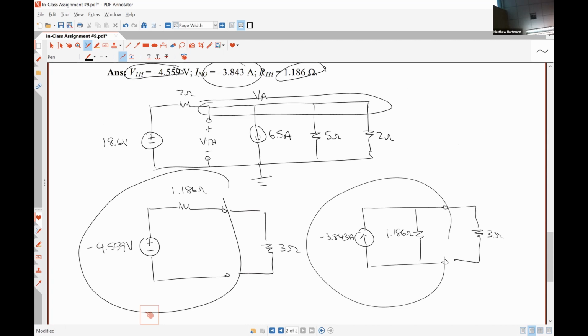So we made everything that isn't the 3 ohm resistor look like either this Thevenin equivalent circuit or this Norton equivalent circuit. On your exam, when I ask you to work problems using the maximum power transfer theorem, using the Thevenin and Norton equivalent is a possibility, in addition to potentially just using multiple iterations of source transformation. They are two different ways of breaking down a circuit into a practical voltage source and a practical current source.